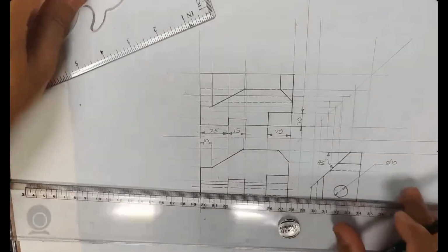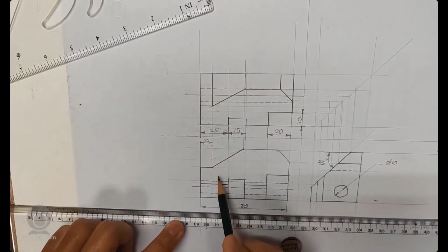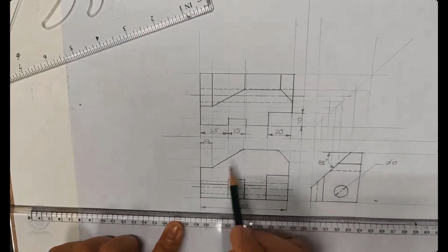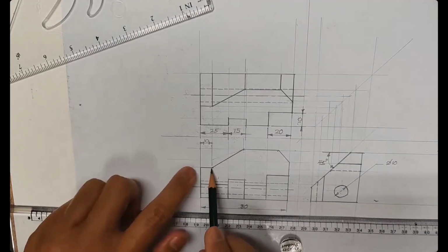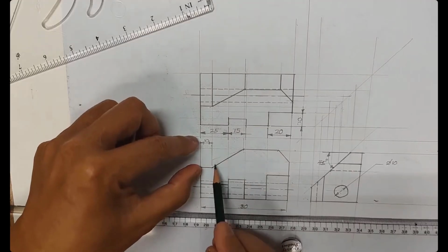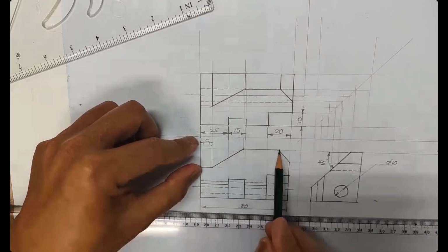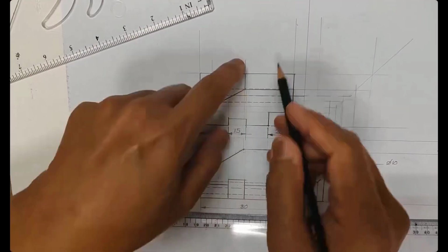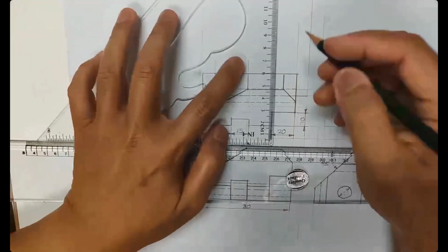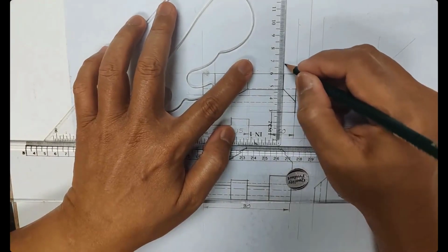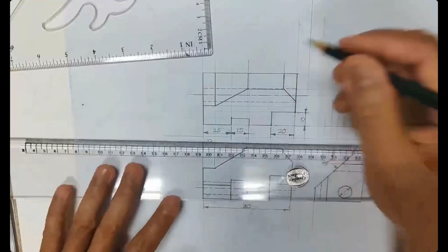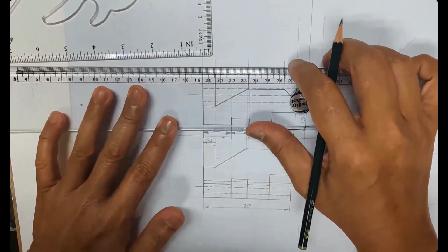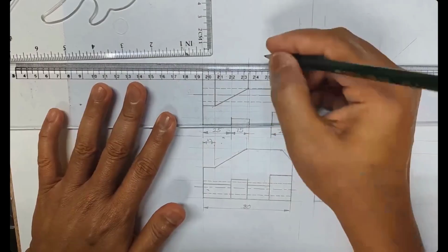All right, for this one, to show the chamfer, 10 and 10, the features of the chamfer, the distance 10 is better put on the front view. But I have a distance here of 20. I don't have space to put 20 here, but you are allowed to put 20. I just need to show you quickly. Maybe I do it not that big. You have to extend the line, not too close, 2 letter height, not too far away. The distance is 2 letter height.